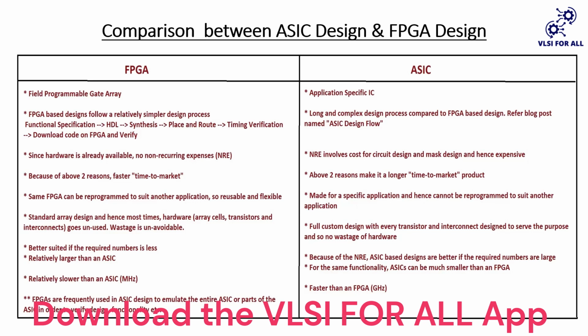But in ASIC the initial cost is very high, because in ASIC designs we have to go through more steps, like verification, and then photolithography processes when we deploy our designs in an IC. Basically, the fabrication process is heavier in ASIC design, so it is more complex and takes more money in the initial stage.